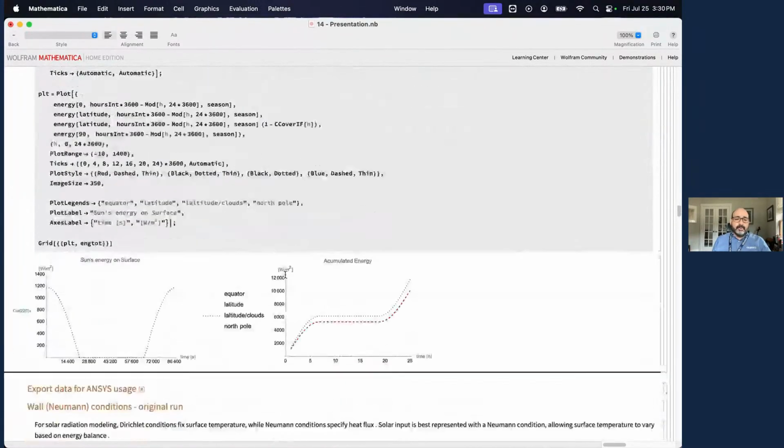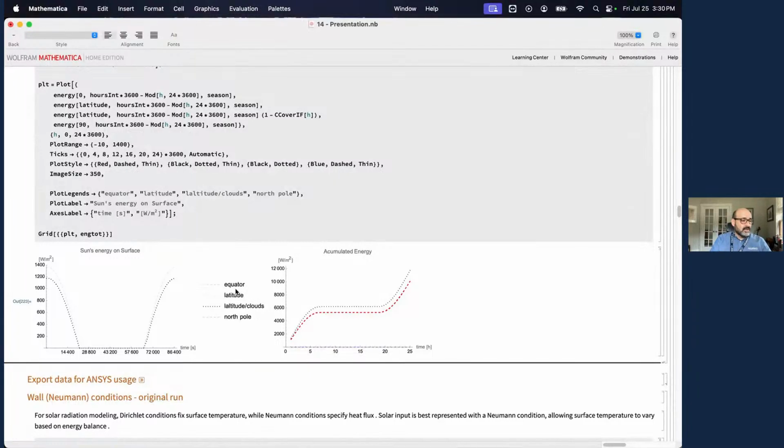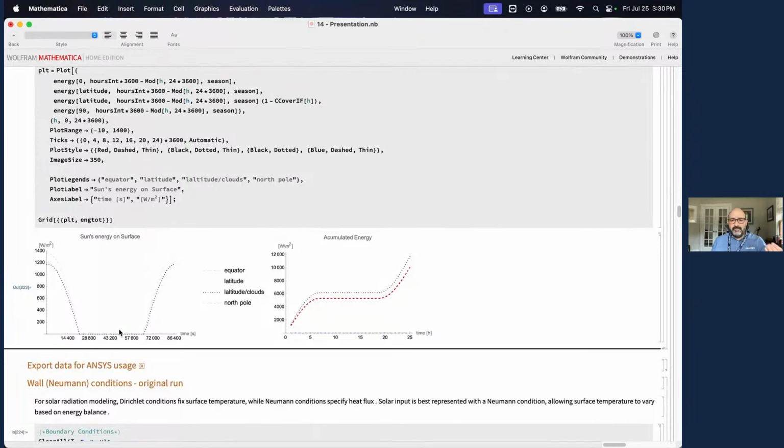Okay, so final radiation model. Radiation is important to know at what time you can start collecting water, and at what time you will stop collecting water. And obviously, as soon as the sun goes down, you will start collecting water. Now, if you live in coastal areas, you'll see this. Every day in the morning, you'll see water condensing on your cars, on your windows, etc. And this happens around the world. And under certain conditions, you can even generate water in the desert, because the desert gets so cold at night because of the exchange of radiation, and there's a little bit of humidity. You can condense water there.